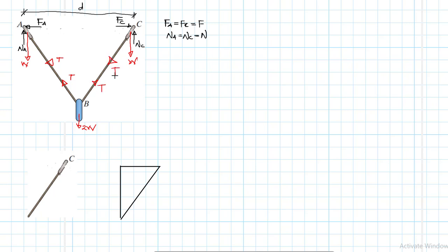These are going to be equal. Then I will have an angle in between here, which I'm going to call theta, and it will be equal to another theta there. So this wire is free to move about point B because this ring is behaving like some kind of a pulley, so it will readjust itself so the tension on the left hand side is equal to the tension on the right hand side.